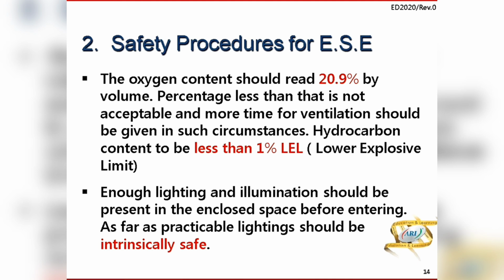When you check with your O2 analyzer, oxygen content should read at least 20.9 percent by volume. Any percentage less than this is not acceptable, and more time for ventilation should be given. Hydrocarbon content should be less than 1% of the lower explosive limit. There should be enough lighting and illumination in the enclosed space prior to entry, and the lighting should be intrinsically safe. The torches which you carry should be intrinsically safe.